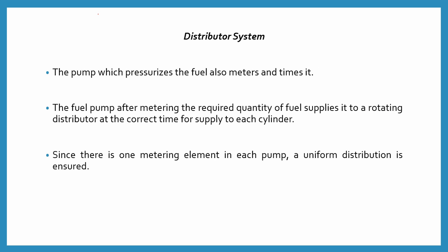Now coming to another kind of fuel system, which is called the distributor type system. The pump pressurizes the fuel and also meters and times it.